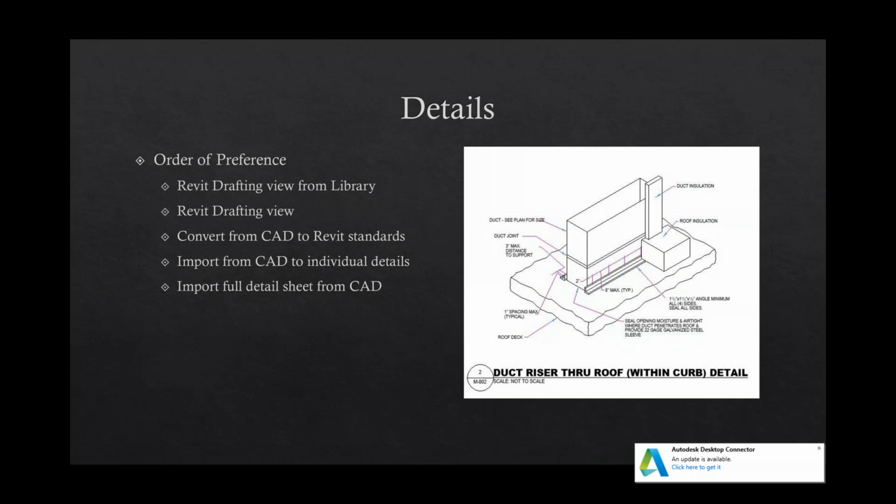This is a hard pet peeve. If you ever import AutoCAD, you have all your AutoCAD line styles in your Revit file, and you cannot get rid of them. So if you ever do import AutoCAD, do it into a separate file. Do your converting there, and then copy and paste the new Revit content into your actual working file. Anything else, you'll regret that.